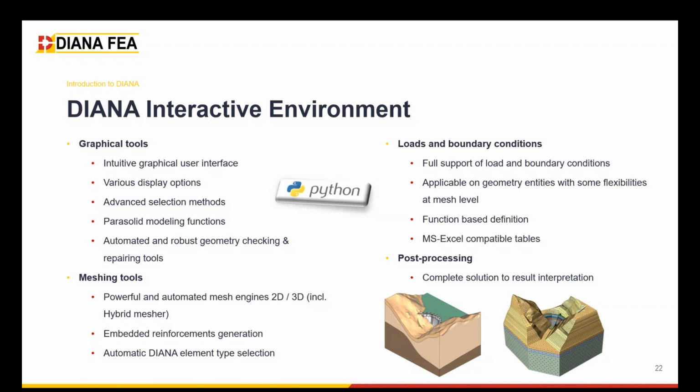In terms of meshing tool, we have a powerful and automated mesh engine, 2D and 3D, including hybrid mesher. We have automatic generation of embedded reinforcement, piles, and sheet pile walls and anchors.